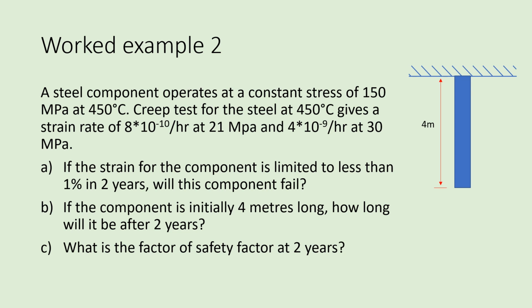And we have 3 parts to this question. First, if the strain for the component is limited to less than 1% in 2 years, will this component fail? 2, if the component is initially 4 meters long, how long will it be after this 2-year period? And 3, what is the factor of safety for this 2-year period?